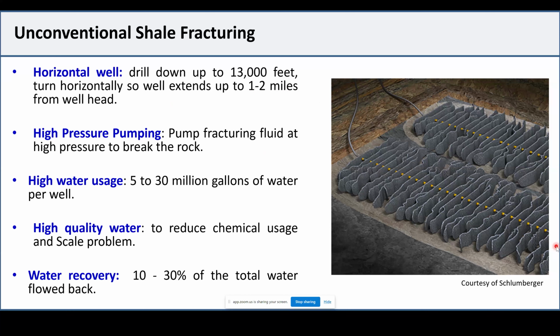With that many fracs, you are talking about a huge amount of water usage, going from 5 million up to 30 million gallons of water just to treat one well. And this fracture, unfortunately, needs really good quality water. The better the water quality, the less chemical you will use from the frac point of view, and the less scaling issue you'll have. That's the current trend.